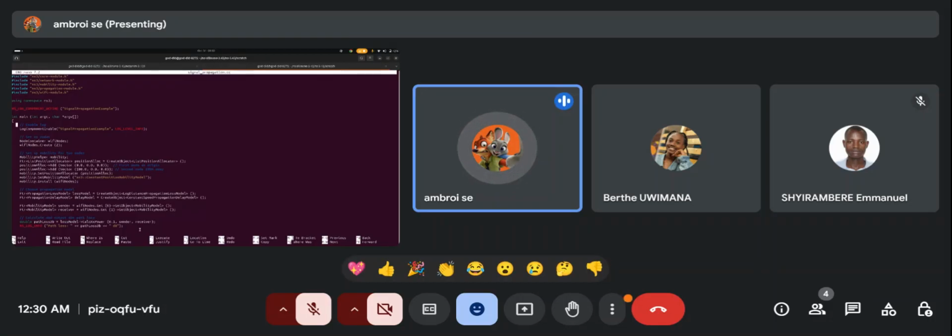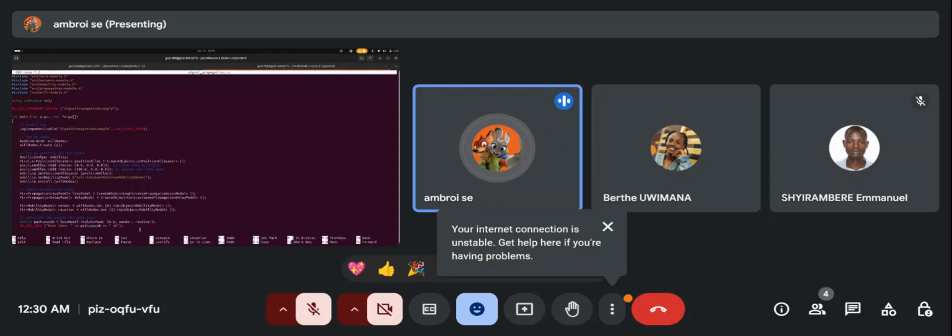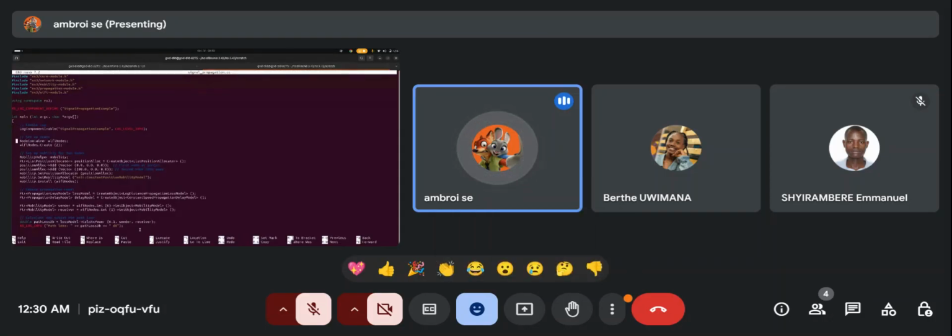The next section is the node container. This node container is called WiFi node. We have two nodes in the node container called WiFi node. This represents devices in our simulated network.